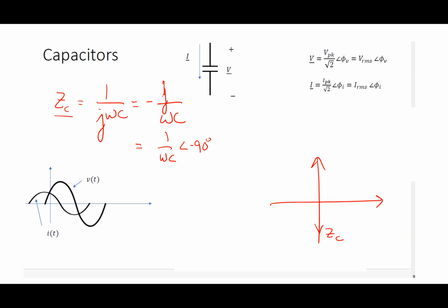Okay. Now, if I want to relate the voltage and the current there, V equals I times Z. It's basically the complex form of Ohm's law. We're going to use this a lot. How many equations is that? Trick question. Is that one equation? It's 2, right? Because it's complex. What are the 2 parts? There's a magnitude and an angle piece here.